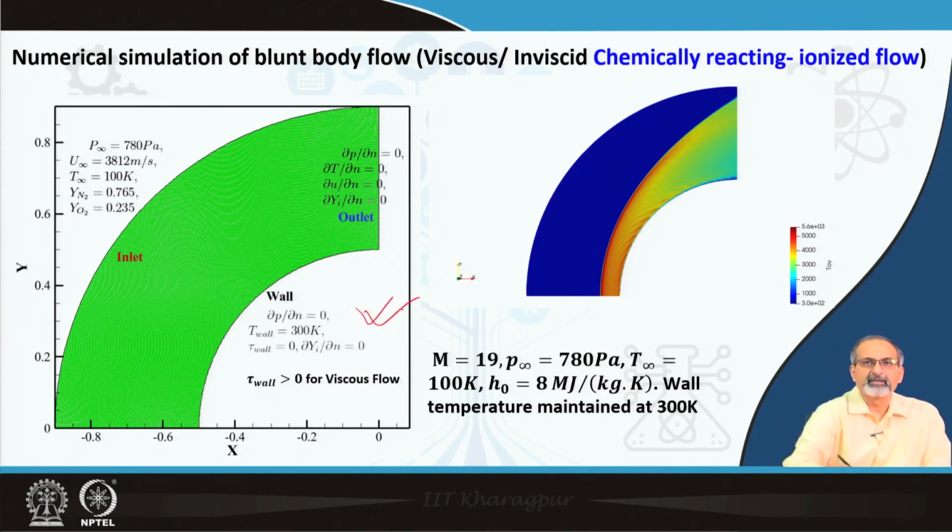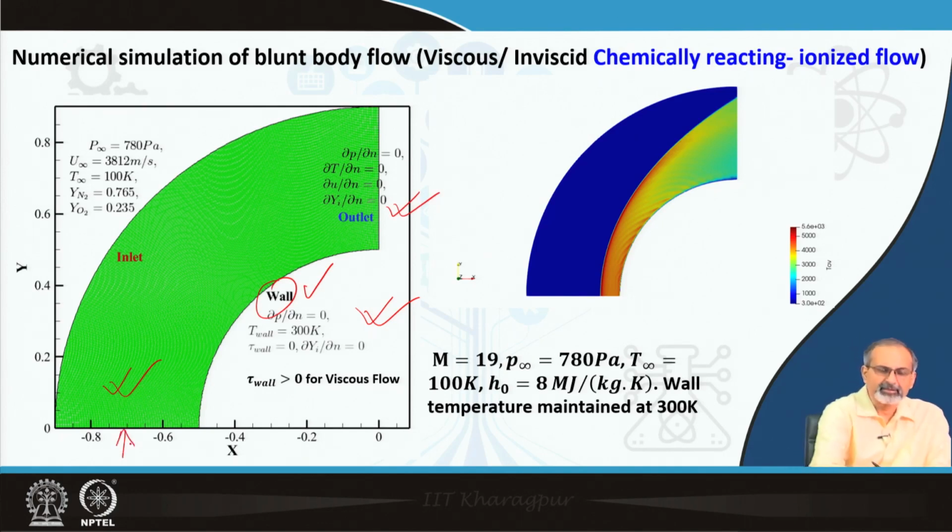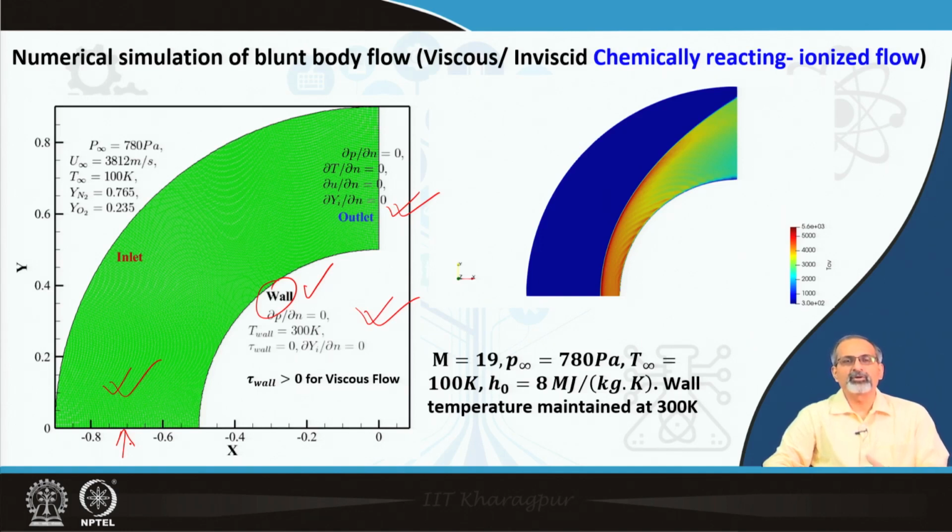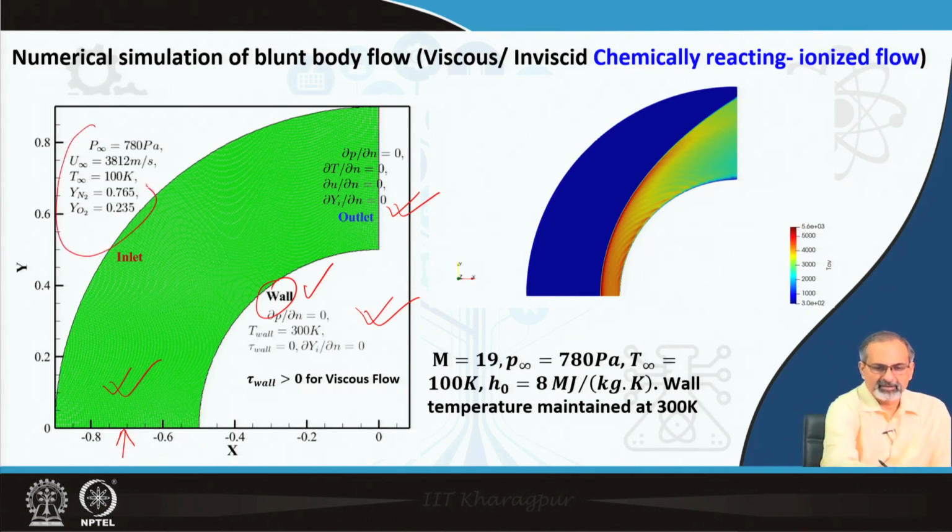It is basically a circular cylindrical geometry. This is the flow domain, which has been defined with the inlet coming from the free stream end. We have the body, the wall at one end, and the outlet at the other. This is more like a symmetry boundary, above and below which the geometry or the flow would behave identically, in terms of a kind of mirror imaging, and then different free stream conditions are defined over here: